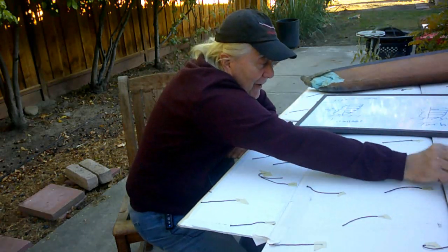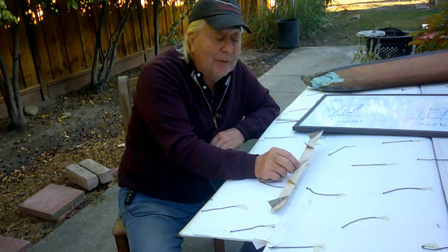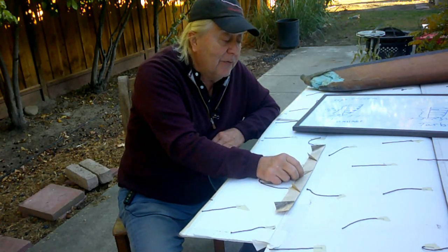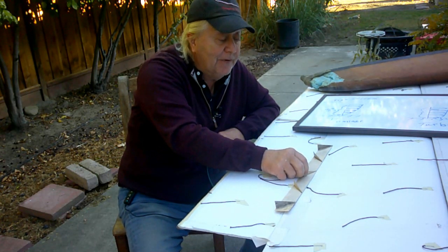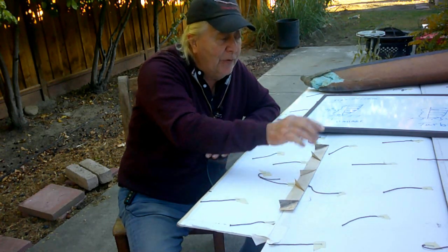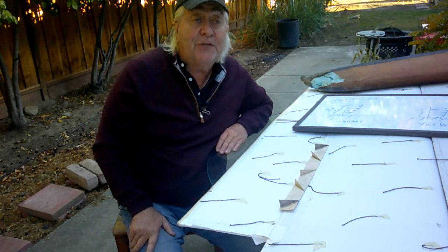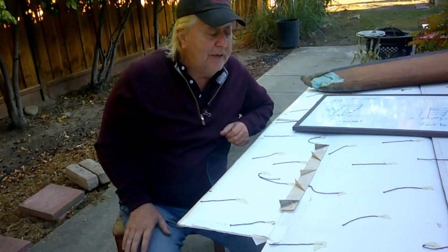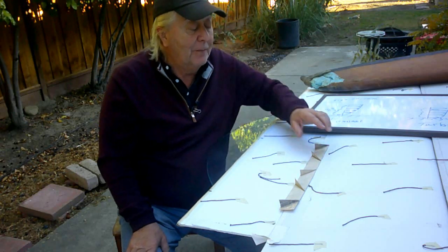So if I have vortex generators on here, to really get good performance out of my wing, they're going to need to be retractable, which I could do. I could interconnect it with a flap. So when the flap's down, they're up. They're generating little vortices, keeping the flow attached, making that turbulent boundary layer. And then as I pull the flap up, these would retract down inside the wing. The mechanism could be made lightweight enough, simple enough, where it's just a spring-loaded pull string type situation, and they go up, they go down. And you'd put them back out for landing. Eminently doable, but not without making very significant modifications to my wing.